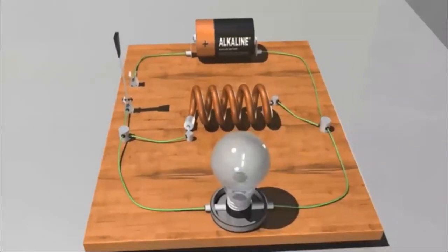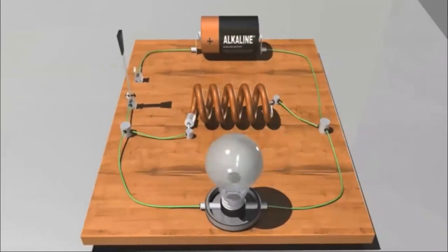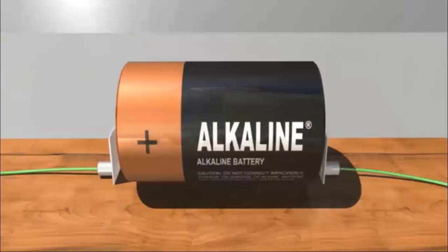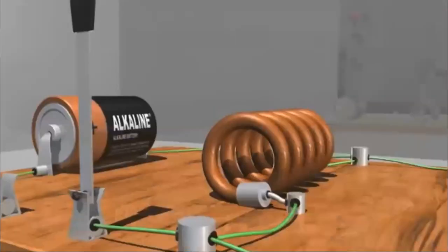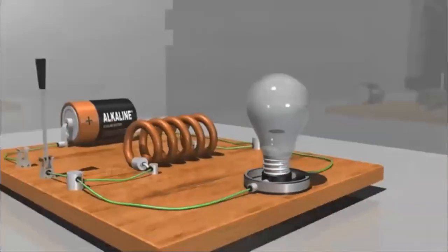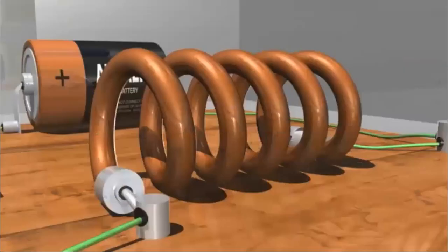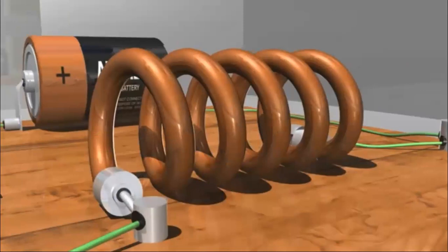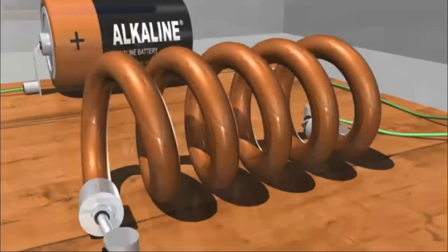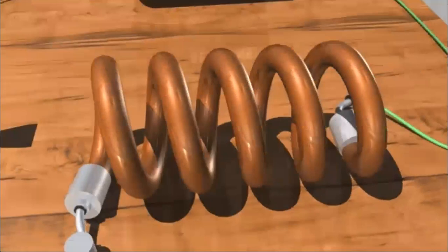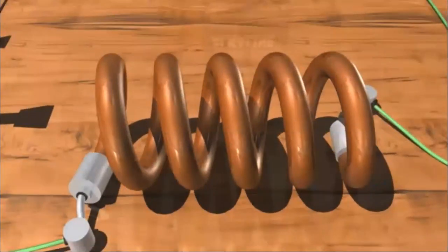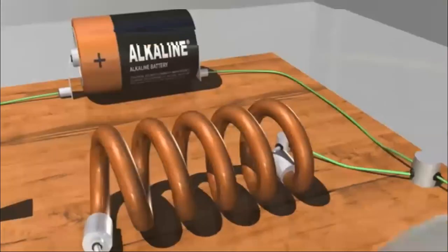In this way, current will flow in the coil when there is a relative motion between the coil and the magnet. For example, if you have a magnet and you move it relative to a coil, you can create a current. On the other hand, if you connect the coil to a battery, the current going through this circuit will create a magnetic field around the coil. So the wire coil will serve as an inductor, since it will induce a voltage in the coil when its magnetic field changes.